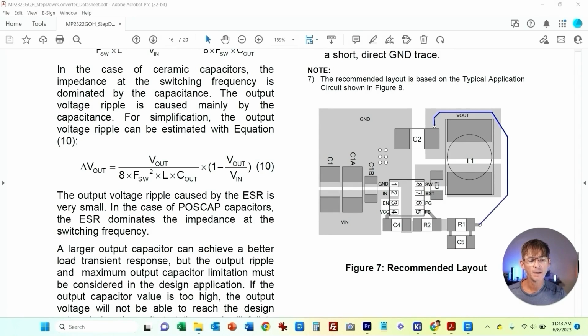And keep in mind that the switch net was one of the high current nets that we need to use a copper pour for. So here we have our fourth copper pour, because you have ground, V in, V out, and then the switch here. This copper pour grabs the bootstrap capacitor and it grabs the other side of the inductor. And that forms the fourth copper pour.